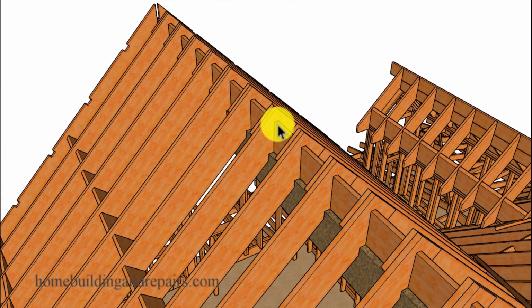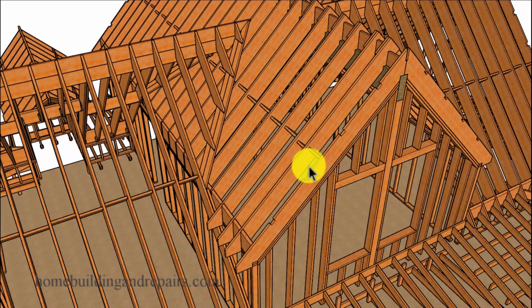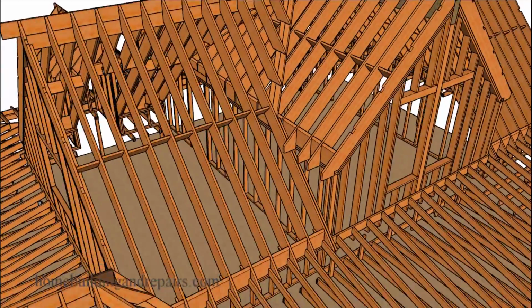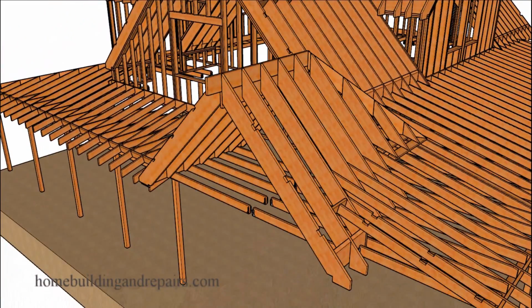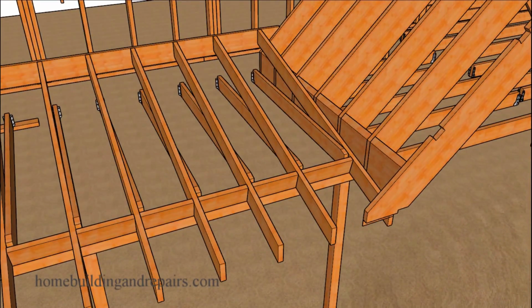And of course our rafters will lap here, and since we are working with a 45-degree angle here, the ends of these rafters will be square on each side, which might make it a little easier to cut the roof rafters. And of course our mid-span blocks that we have here usually go in the middle of the span of the common rafter.